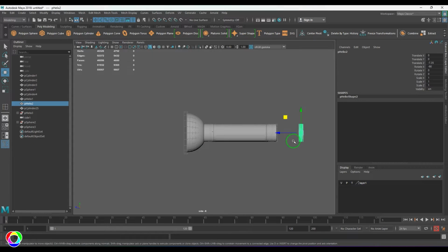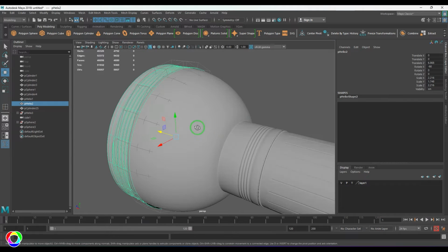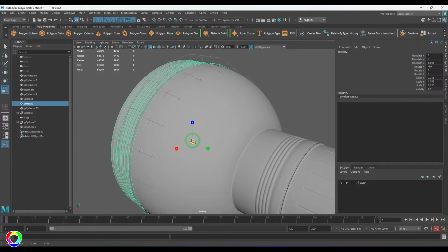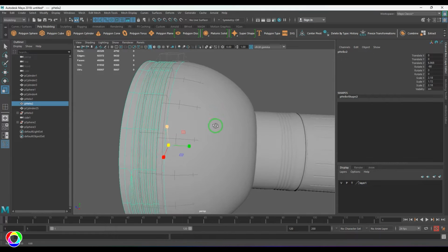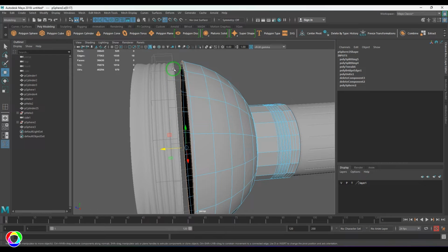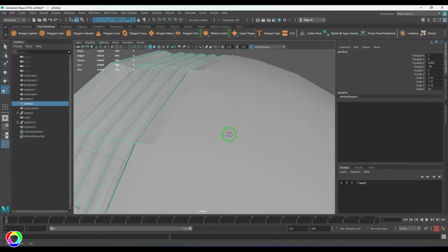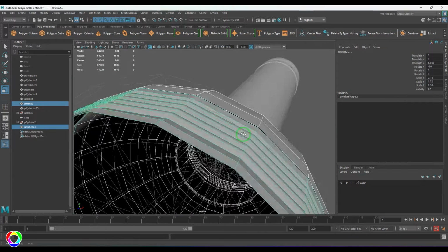We have the screw thread pattern, so I need to scale this, and I'm going to place it here, and I'll be roughly moving this point there. So I'll select this, and then using point snap I'll snap it to that level, and then I'm going to scale this one, and I should be able to see both have almost the same size.